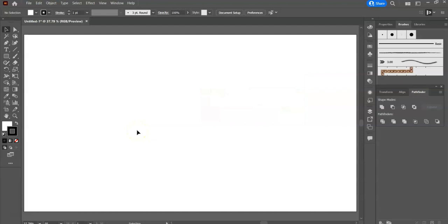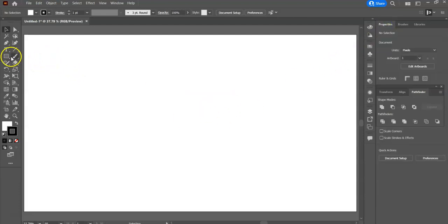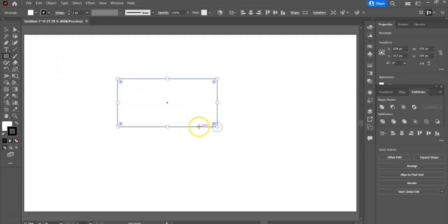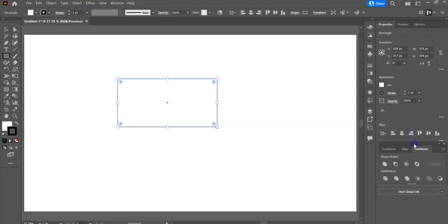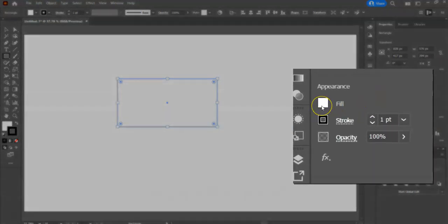Next, let's review stroke and fill. There are several different ways you can change your stroke and fill, and I will show you just a couple. If you have already drawn something on your artboard, you can look at the properties over in your properties panel. That includes the fill color, the stroke color, more settings here, and then the stroke weight right here.